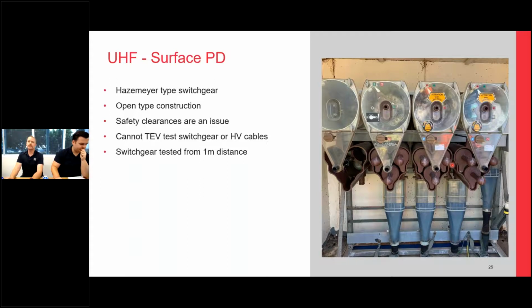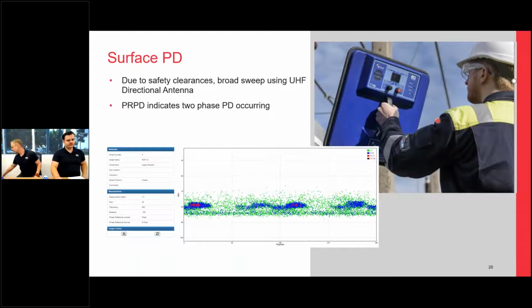The next test we did on this one here was a UHF test. So what we were able to do was stand about 1 or 2 meters back, point the antenna at the switchgear, play with our settings and tune in to some PD activity that was occurring.